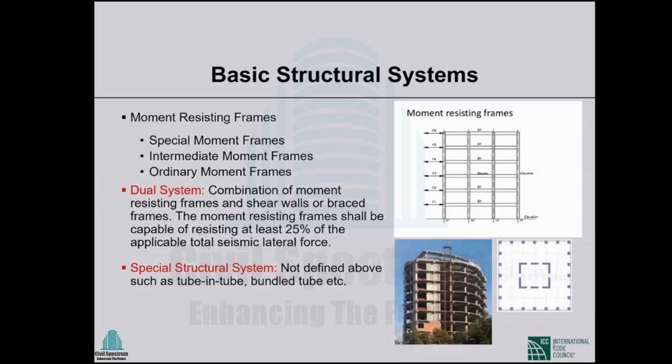So ordinary moment frames are not very ductile. They collapse after some deformation. Intermediate moment frames are somewhat more ductile than ordinary moment frames, and special moment frames are very ductile. So they can absorb a lot of energy during inelastic deformation. So we'll see some more details. Actually, Dr. Ghosh will give lectures precisely on these topics in the later sessions in the coming weeks.